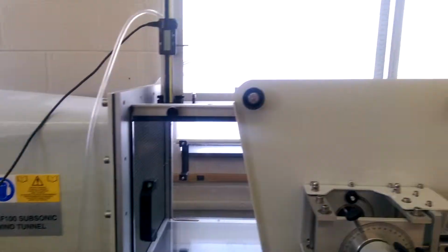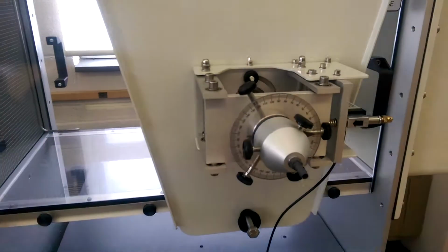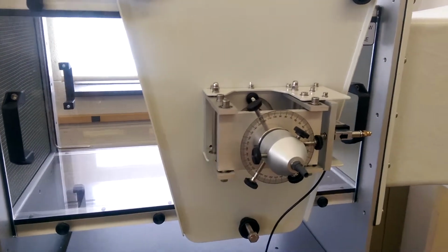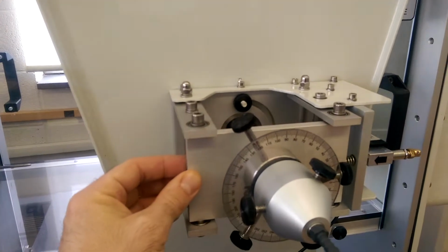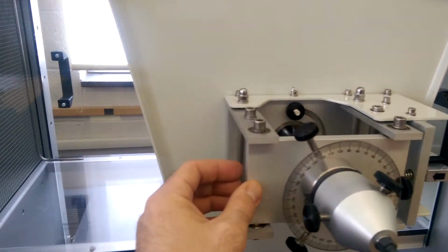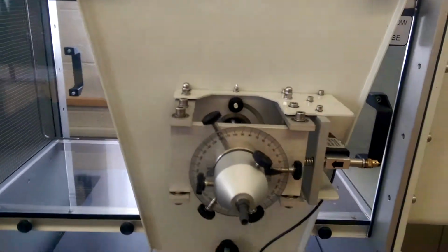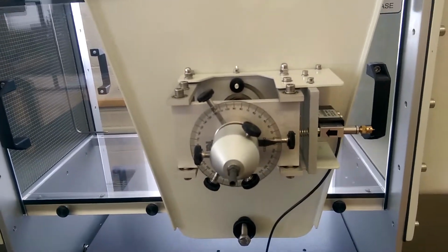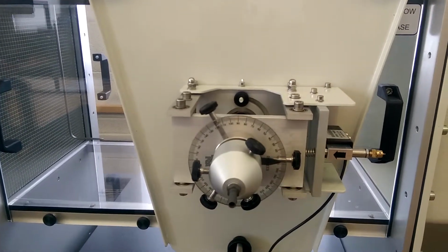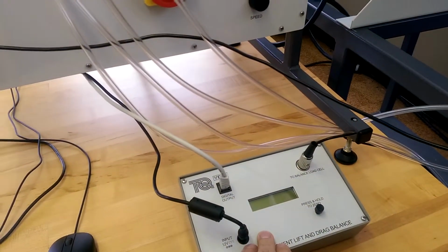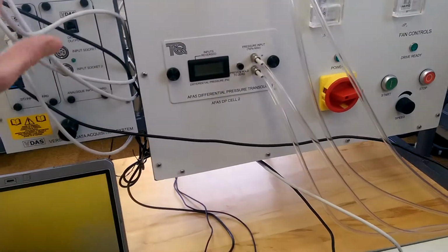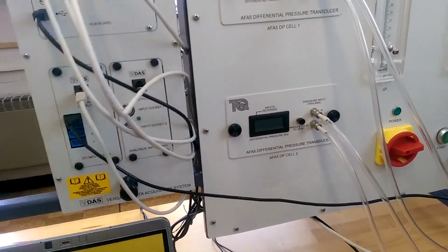In addition to the pitot tubes, there is also a single balance force transducer. This particular force transducer is oriented in order to measure the drag force of the cylinder while there's wind blowing in the test section. This single force transducer is connected to a display on the workbench, which is also connected to a DAQ system.